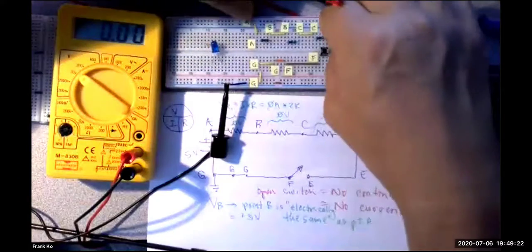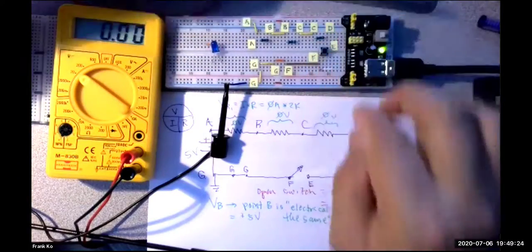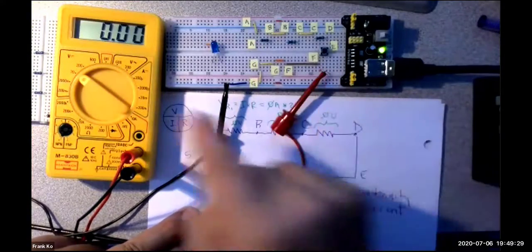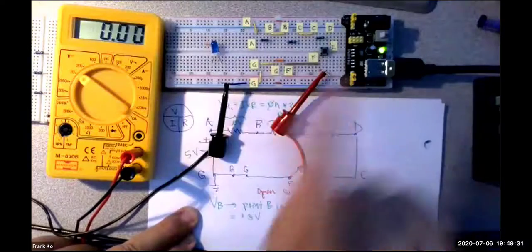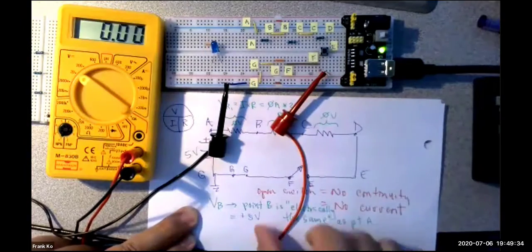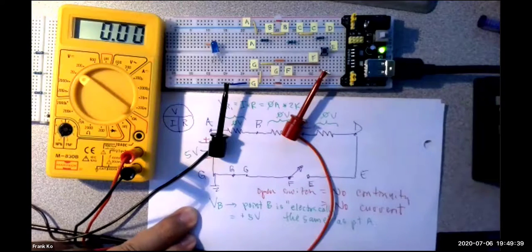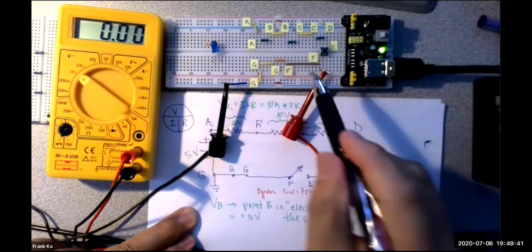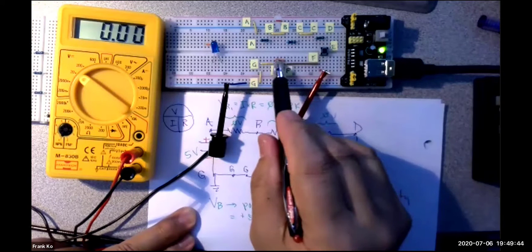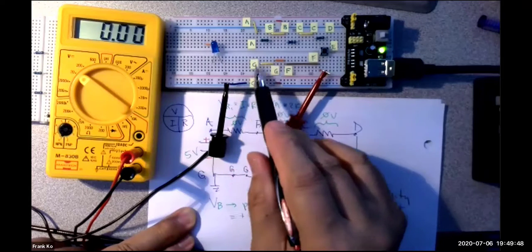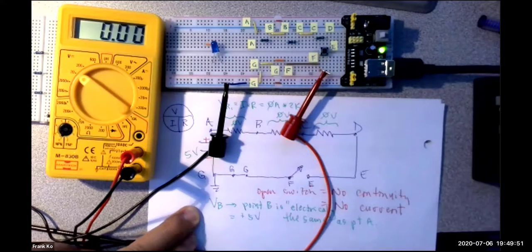0. 0. And if I put this red anywhere on this side of the switch, here's F, and I bring my red probe here, I get a 0. My power supply is clearly on, but I'm going to get a 0 because I am now on a straight piece of wire between F, through this wire, through this jumper where the LED used to be, through this jumper to the rail. This is nothing but a solid piece of wire.